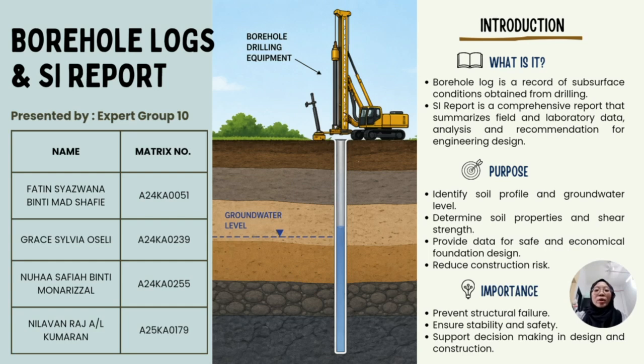So what are borehole logs and the SI report? A borehole log is a record of subsurface conditions obtained from drilling, while an SI report is a comprehensive report that summarizes field and laboratory analysis and recommendations for engineering design.